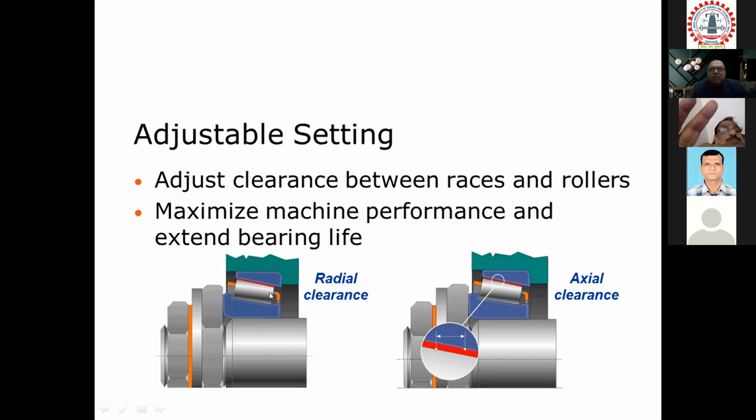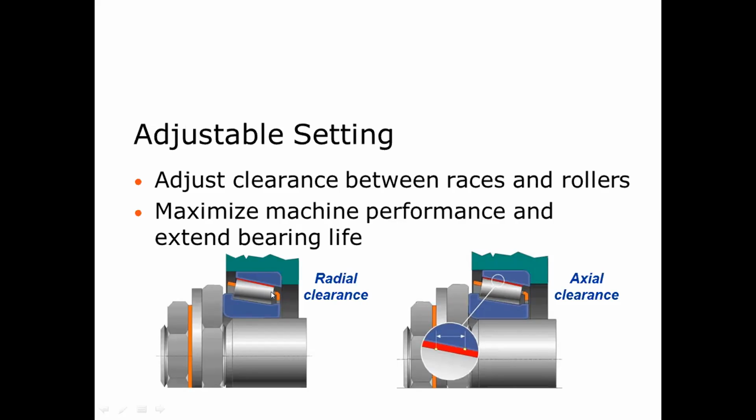In fact, this technology started only about 20-30 years ago, and it has become so advanced now. They do vibration analysis, they do oil analysis, they do the balancing. And there is also a technology which is infrared thermography, with which you monitor the temperature. So these 4 or 5 technologies together are used for doing the predictive maintenance for the bearing.